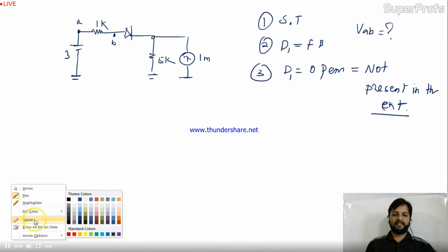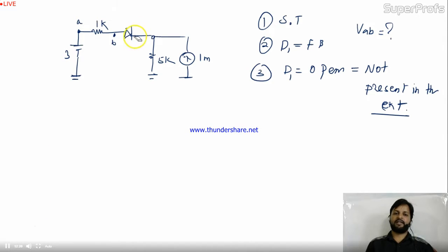In the last technique, the second method, what we assumed is that the diode was short circuited. Here assume that the diode is not given in the circuit. The rest of the things are as they are. 1K is given over here. The diode is not over here. Just assume this. These 2 points are given and we don't have any diode over here. So in the open circuit, please find out the voltage at this point. If this is open, this 3 volt is coming over here.